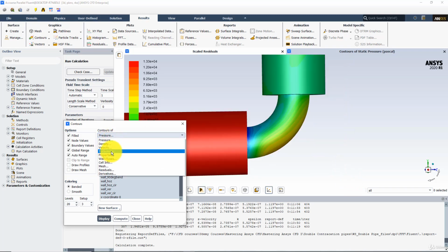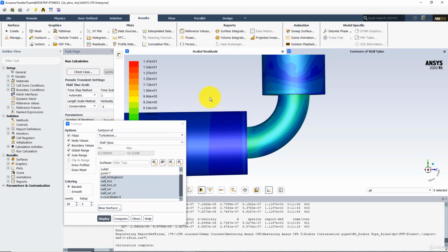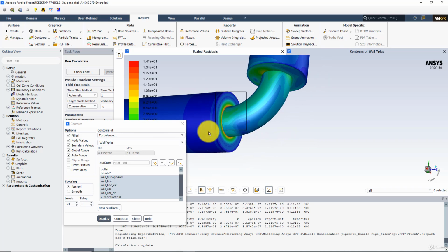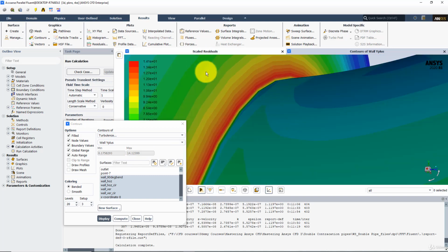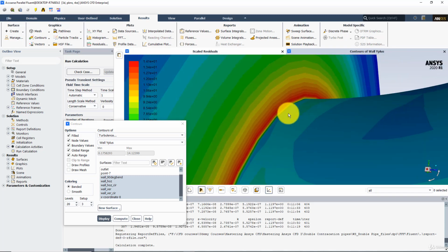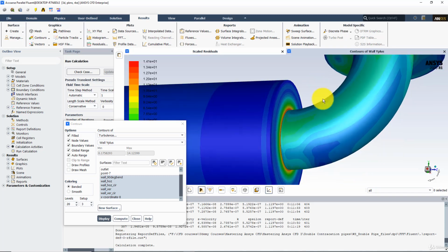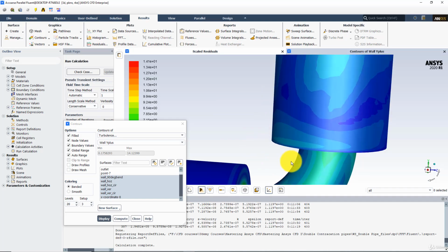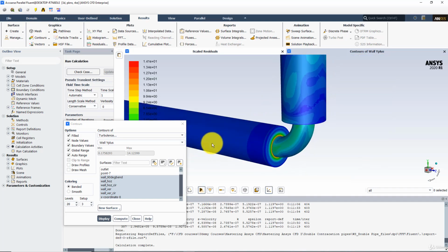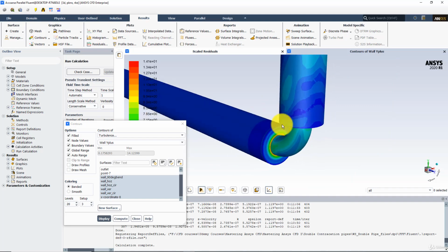And if I check the y plus values, or y star is the same, we can see now the maximum value is around 14.12, and this is because at this region we have the rushing of the flow and it is increasing velocity, therefore with high velocity we have a high value of the Reynolds number and a high value of y plus, and the same is the case in this region. So we can expect these values.